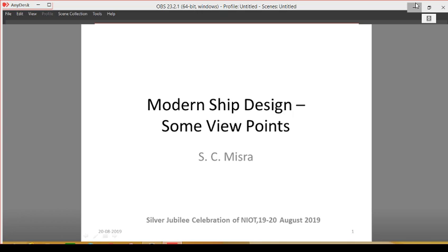When you talk of designing a system, we do the designing in stages. The first step is what we call a feasibility study. We see whether such a thing is feasible to make or not. Then we do something called a concept design, where we broadly fix the parameters and say that this can be built and this can be manufactured within certain cost parameters. The next step is what we call basic design, and then we come to detailed design, to which the item is manufactured.